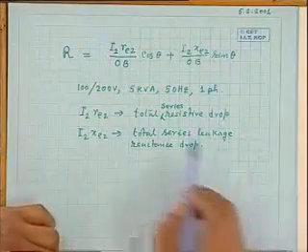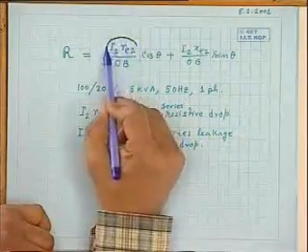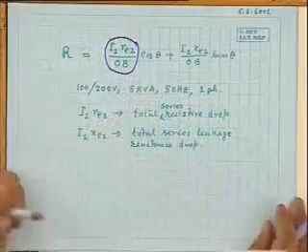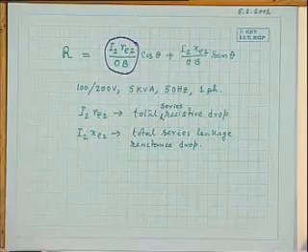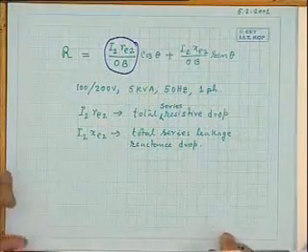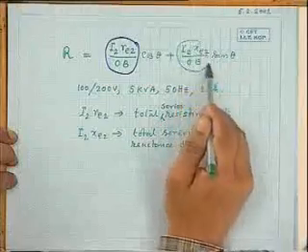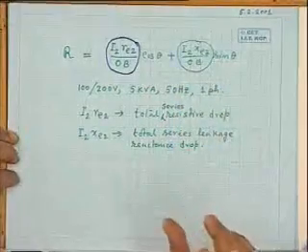So we can now assign some physical meaning associated with this ratio. So this ratio gives me what? It gives you how much of the rated voltage is dropped in the resistance. OB is the rated voltage of the secondary side, is it not? How much of it in per unit sense is dropped in the resistance? Similarly, I2 XE2 by OB will give you how much of the rated voltage is dropped in the reactance.